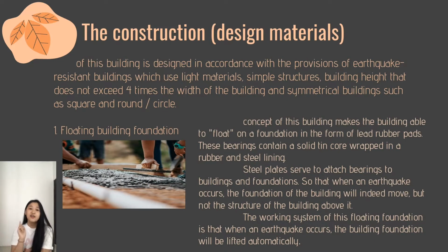Next, the construction or design material of this building is designed in accordance with the provisions of earthquake-resistant buildings, which use light material, simple structure, building height that does not exceed 4 times the width of the building, and symmetrical buildings such as square and round or circle.